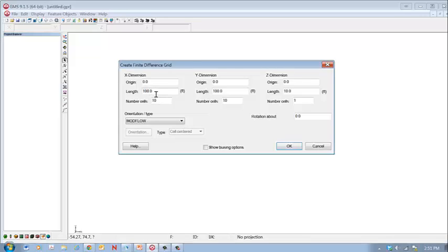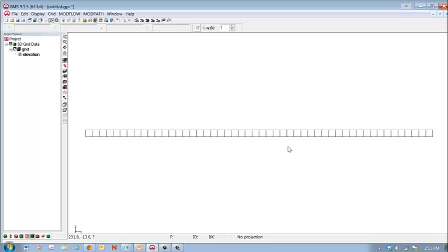Okay, I'm going to set up a GMS model to simulate the conceptual model that we saw previously, and we'll make a grid that is 50 cells in X, 1 cell in Y, and 20 cells representing 200 units in the Z direction.